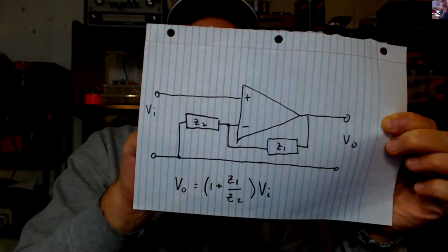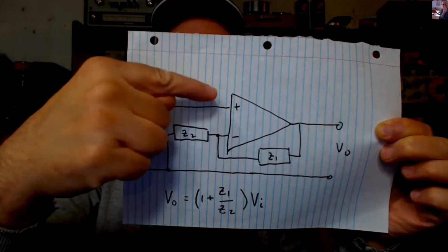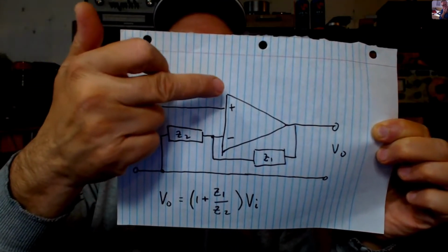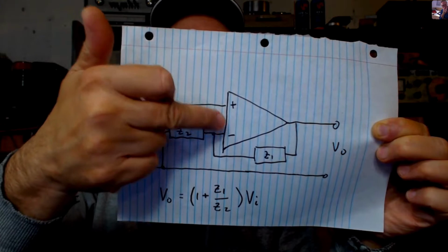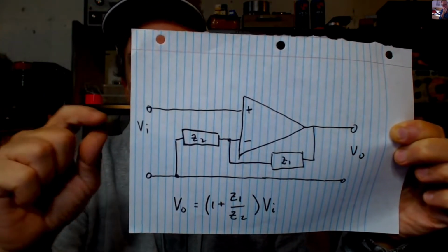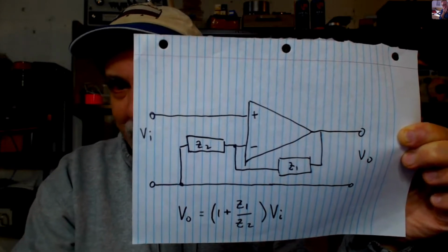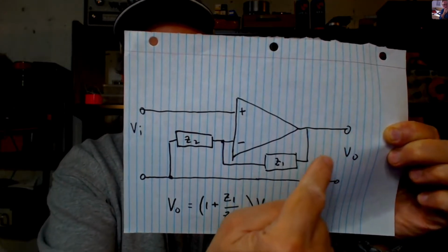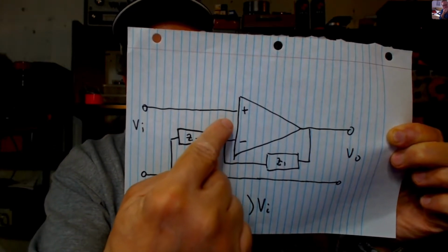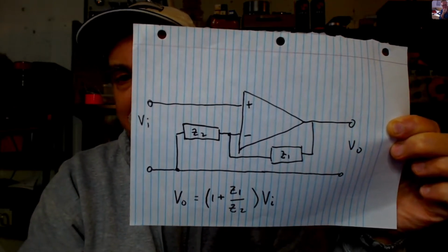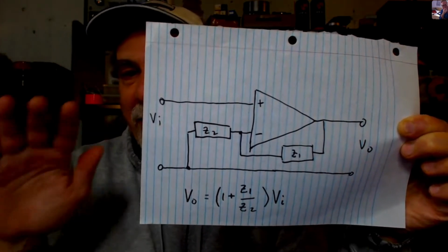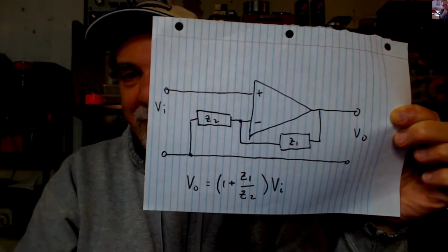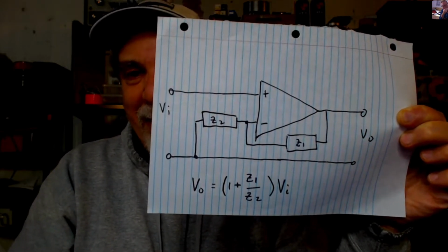Now, what that means, too, is that because this gain is essentially infinite, there's really no difference in voltage between those terminals. That differential voltage is zero. So if that input is grounded, there's your special case of a virtual ground. If the input is grounded, that's at 0 volts, the output should be at 0 volts. Tracing it through, this node here will also be at 0 volts. Everything is forced down to that number because of that miraculous little equation that we get from the very, very large A constant in the op-amp.